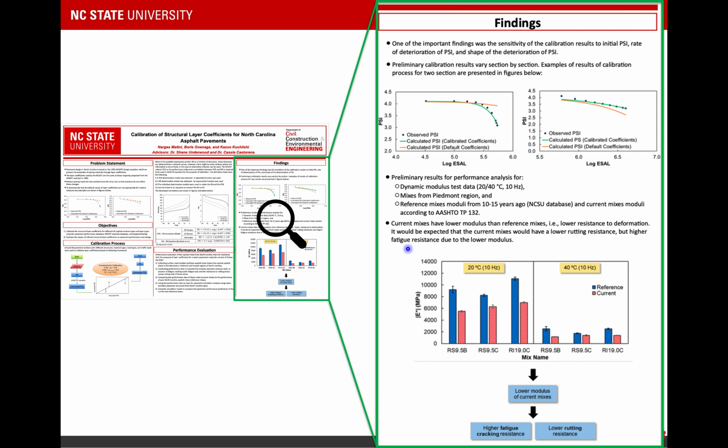Also, the results of our performance tests showed that the modulus for current mixes compared to reference mixes is lower, which means we're expecting to see lower rutting resistance but higher fatigue resistance for current mixes.